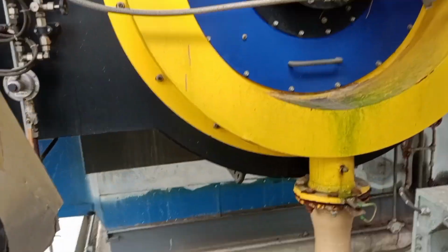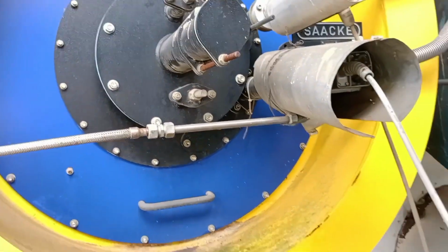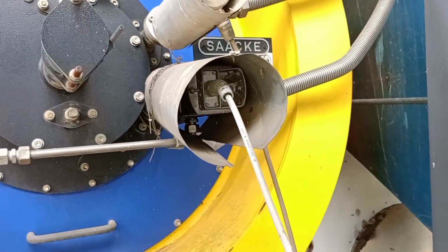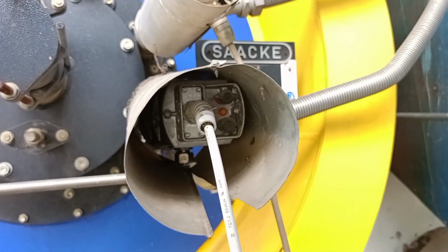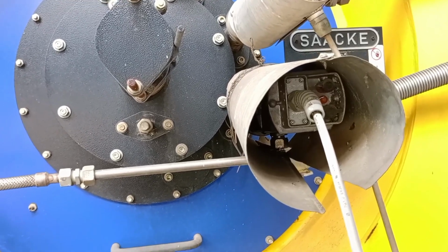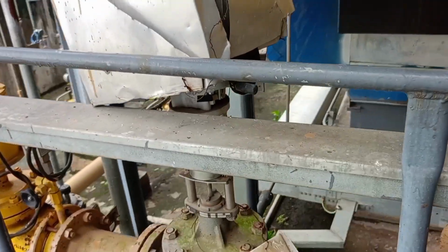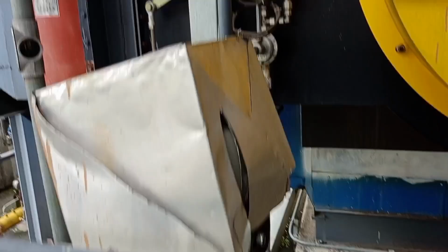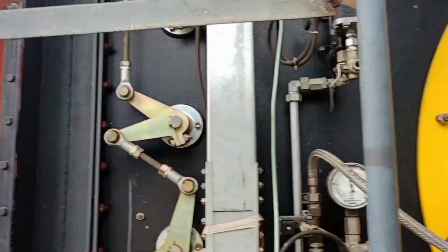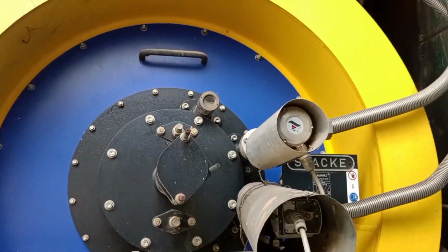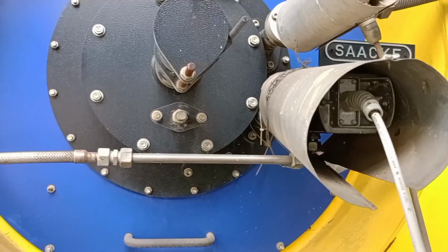And when this gas control valve opens, gas and air pass through this burner or boiler, and there is a flame or igniter, so the fire is already created. So through this air and gas, a large fire is created, and gradually this gas control valve opening percentage is increased, and proportionally the airflow is also increased. So air and gas are regulated and the ratio is slightly 13 to 14. That means the gas to air ratio of 1:13